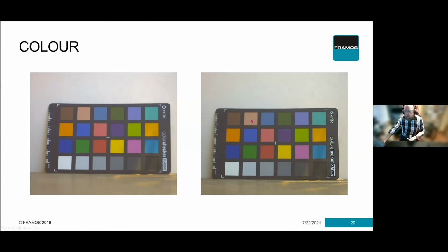So the things that were applied were a CCM, a color correction matrix. This is something needed to take the true data from the pixel, and when you debayer it, knowing the actual behavior of that system, knowing the behavior of those pixels and the color filters within those pixels allows us to make sure we find the truest color representation possible.